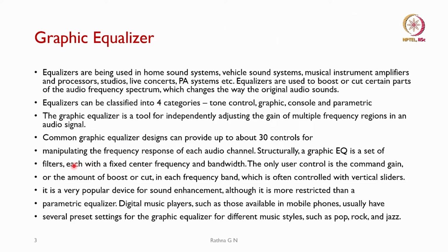If we are designing in the digital domain, each has a fixed center frequency and bandwidth. The only user control is the command gain, the amount of boost or cut in each frequency band, which is often controlled with vertical sliders. It is a very popular device for sound enhancement, although it is more restricted than a parametric equalizer.